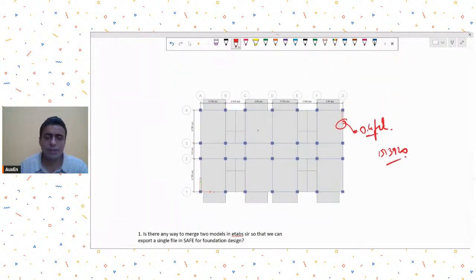So that has to be satisfied. See what will happen in the vicinity of the shear wall: because of the large stiffness, it will attract large movement, and maybe therefore these columns in the vicinity of the shear wall will start showing failures because they are near the shear wall which is attracting. You have made the node common, so they will attract very high axial forces under the seismic loads. That is the reason they might be showing you failure, and that 0.4 FCK clause